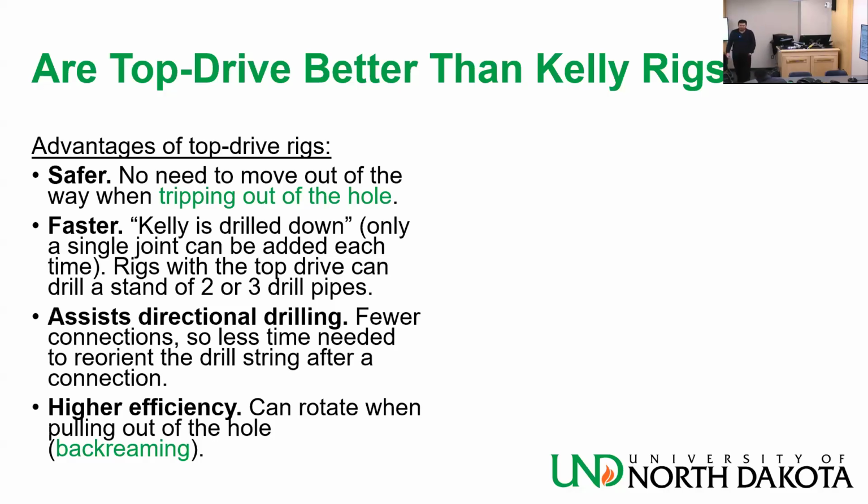connection. So when you do directional drilling, positioning is very sensitive. So you move the drill string a little bit, you might lose the angle that you want to be. Every time you make a connection, you are shaking things, you know? Not only that, you also can get the gas inside your mud system. A lot of things happen during a connection that you don't want. Okay? Higher efficiency, you can rotate while pulling out of the hole, which is called back reaming.